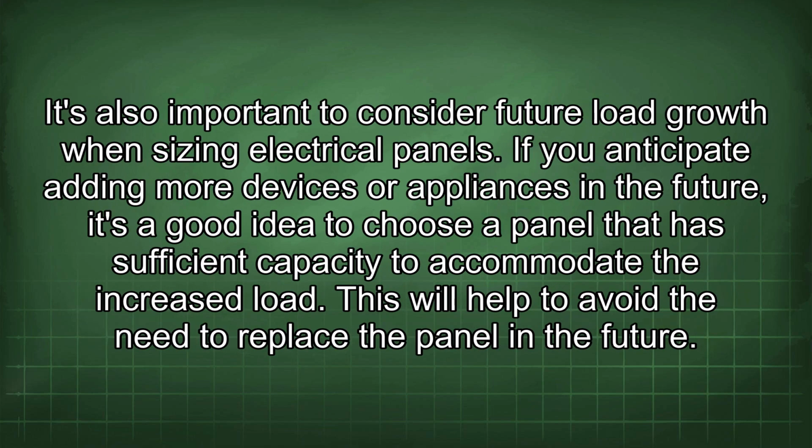It's also important to consider future load growth when sizing electrical panels. If you anticipate adding more devices or appliances in the future, it's a good idea to choose a panel that has sufficient capacity to accommodate the increased load. This will help to avoid the need to replace the panel in the future.